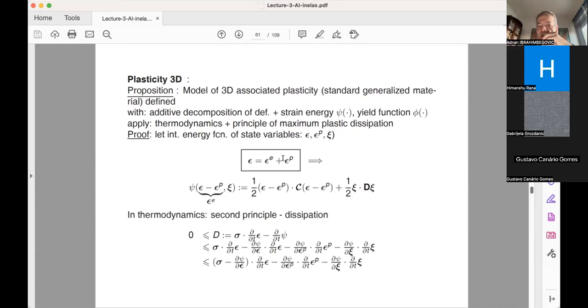And also, instead of the elasticity modulus, Young's modulus E, you're using the elasticity tensor C, which in the 3D case, given isotropic homogeneous linear behavior for the elastic case, needs at least not only Young's modulus, but also the Poisson's ratio. And then hardening is also generalized with some kind of vector type of hardening variables and the corresponding tensor for the hardening modulus that you generalize.